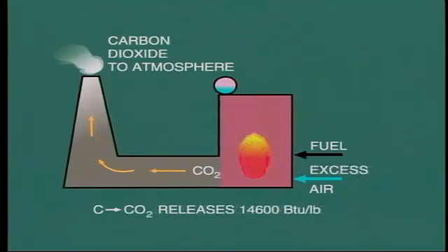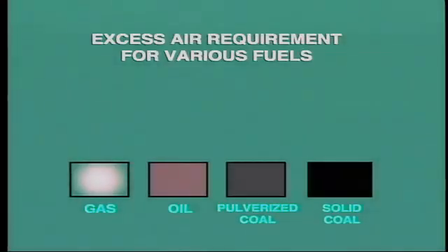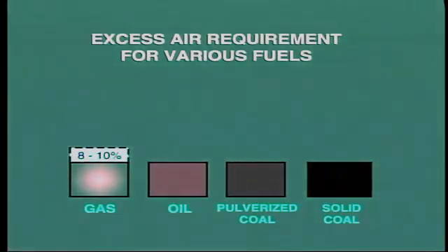In order to ensure that combustion of the fuel is complete in practice, we need to provide excess air. The precise amount of excess air over the theoretical amount calculated really depends upon the type of firing equipment and the fuel itself. Speaking very generally, we may find that natural gas firing requires about 8 to 10% excess air.